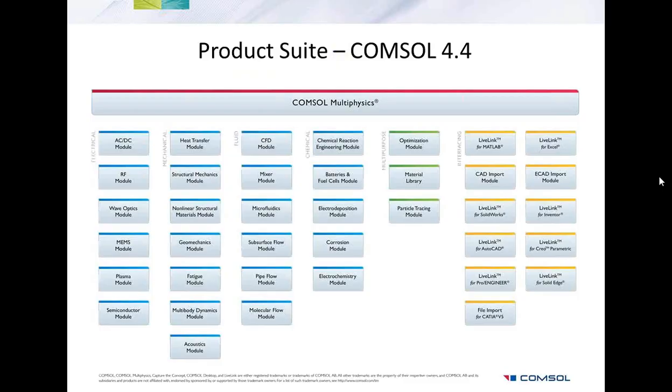Okay, fantastic. Thank you. And so just one last quick question. Can COMSOL be used with HPC? Yes, it can. You can actually use it with Amazon Cloud services or EC2 services, or if you're building your own in-house cluster, you can use them on there. Just bear in mind you need a particular type of license. You can't just have a standalone CPU license. You need a floating network license to run HPC types of studies.